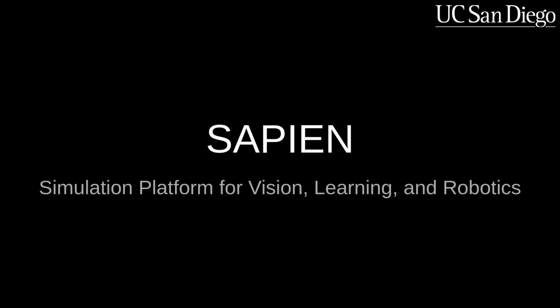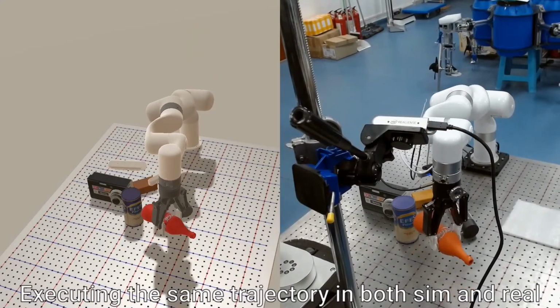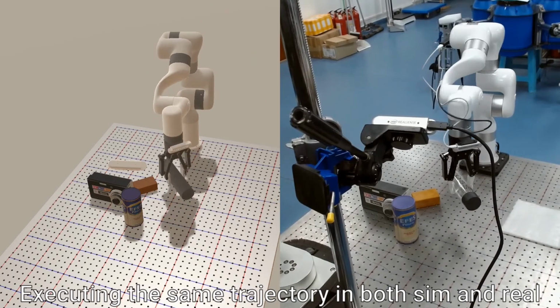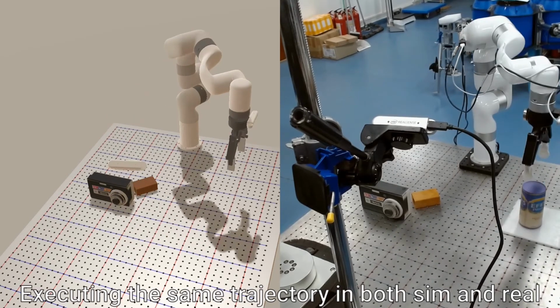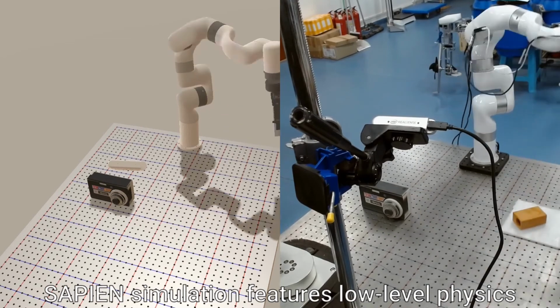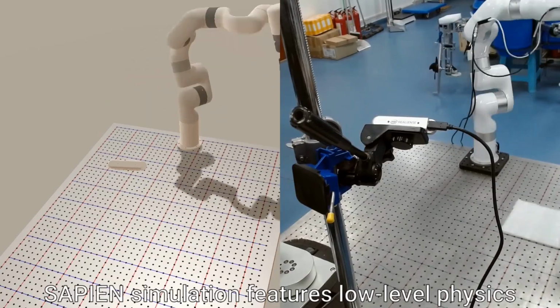SAPIEN is a simulation platform for vision, learning, and robotics research. In its first version, SAPIEN supports physics and robotics simulation, rendering, and provides a large set of assets of articulated objects. The physical simulation in SAPIEN is designed to closely resemble the real world. As shown in this video, the robot in SAPIEN Simulator on the left is executing the same trajectory as in the real world shown on the right side. The simulated objects are manipulated through contact and friction forces, and the robot uses a PD controller to follow the trajectory just like in the real world.